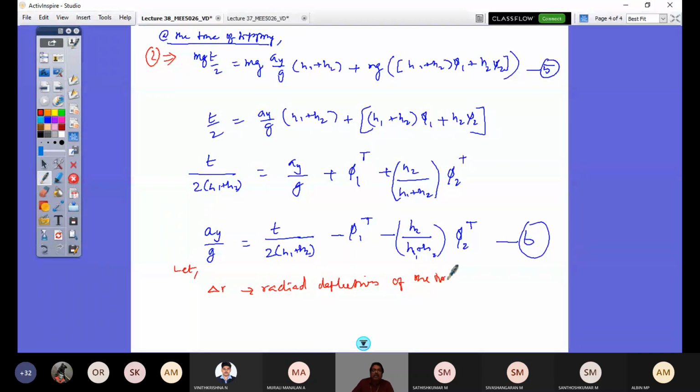See, this stiffness we should differentiate from cornering stiffness. C subscript capital R is the radial stiffness, that is, the vertical stiffness of the tire. You take a tire and you load it. The deflection that you measure is this delta R, and that stiffness, load per deflection, is your radial stiffness of the tire.